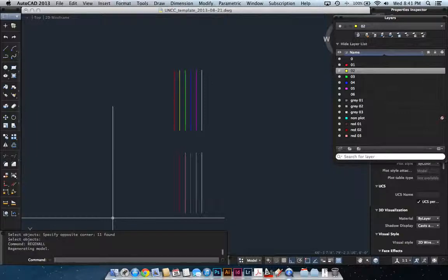And that basically refreshes the entire screen, and sometimes whether it be through the graphics driver, the amount of content within the file, or just simply that particular file, you might lose some detail that's not really quote-unquote lost. It's actually just set up in a way that the simplification of the geometry just made itself apparent, and by hitting regen all, it essentially refreshes the entire visual interface of CAD. It affects your drawing in no way, positive or negative, by regen all, but it can help clear up some visual things if you're getting some artifacting.